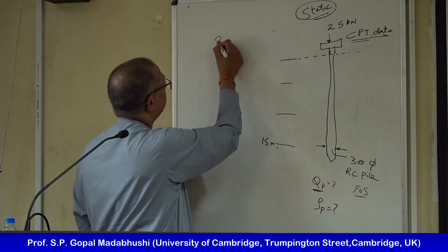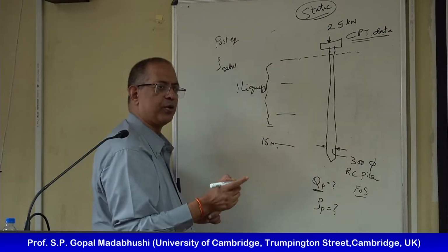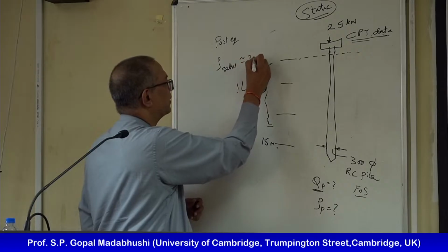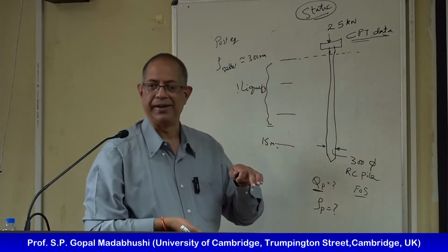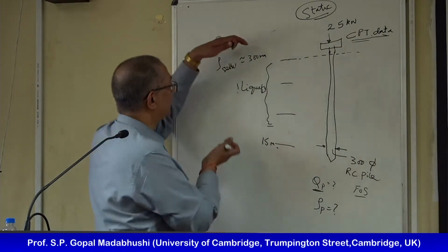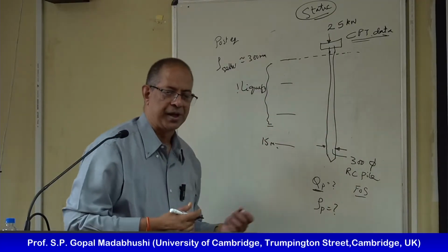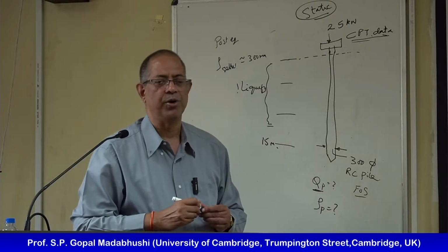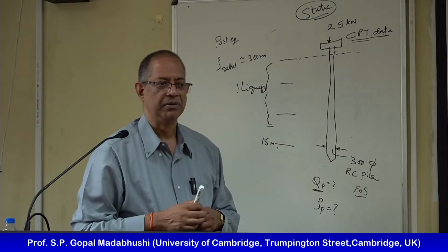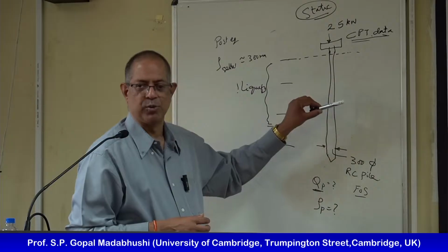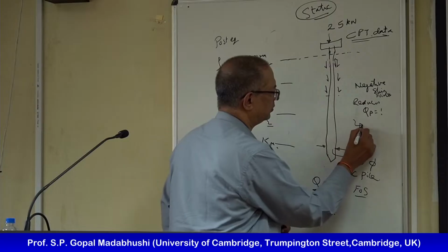But post earthquake, immediately you got about 300 millimeters of settlement of the soil layer, right? So the soil itself is going to settle, but the pile is going to stand proud. So if that happens, what extra load will come onto the pile? The soil wants to settle, pile doesn't want to settle. So what is the new factor of safety?